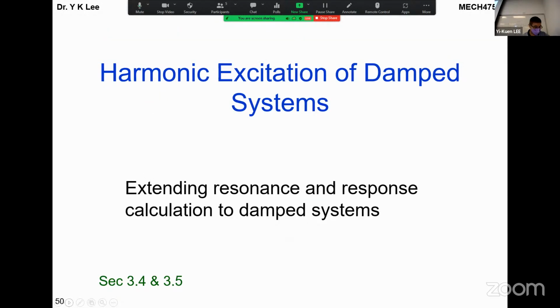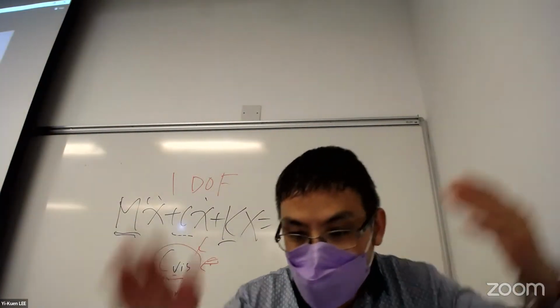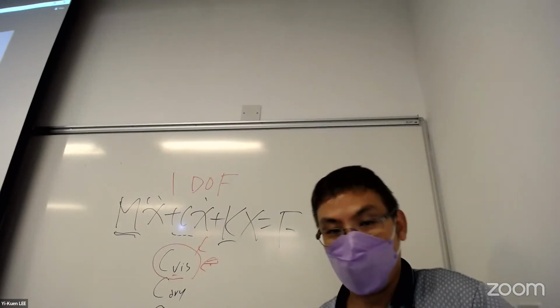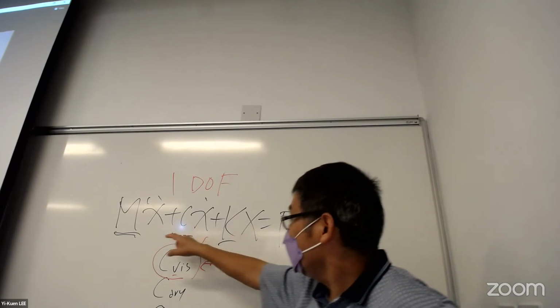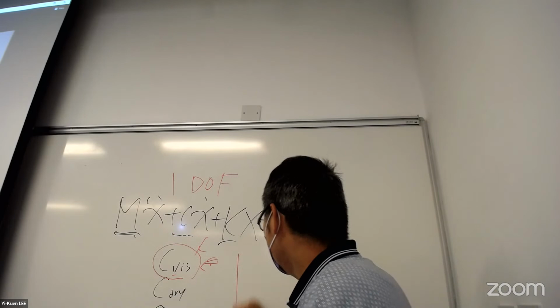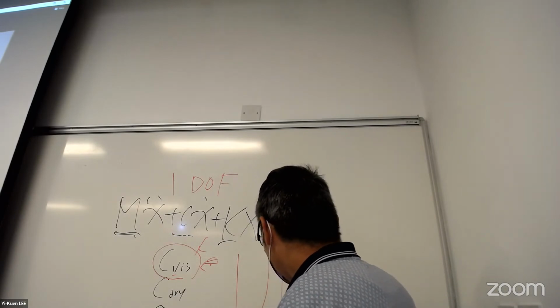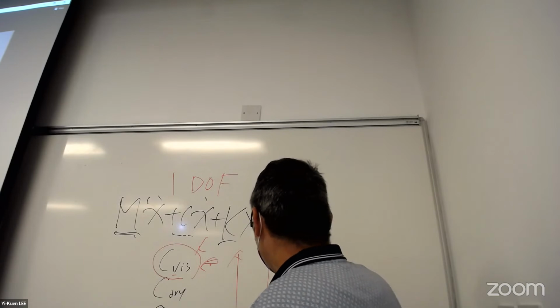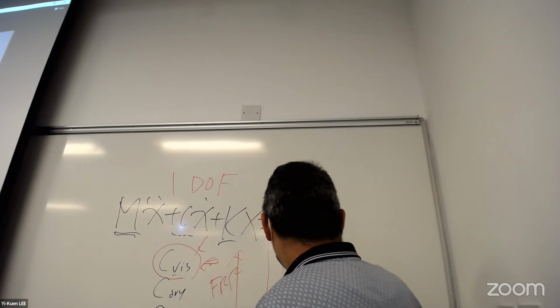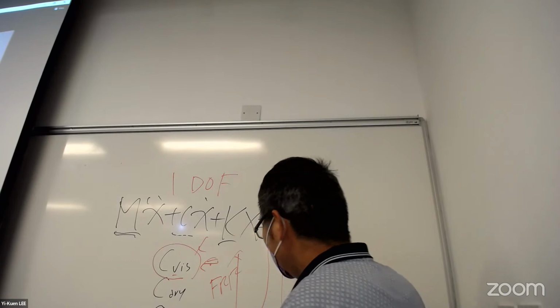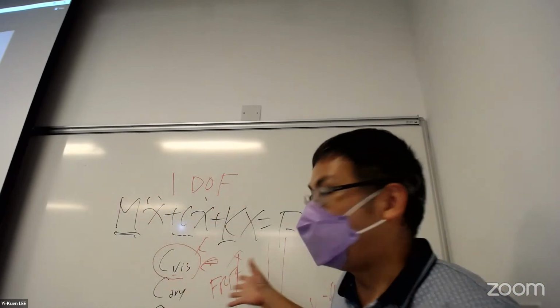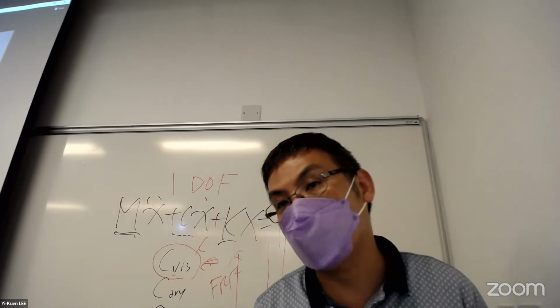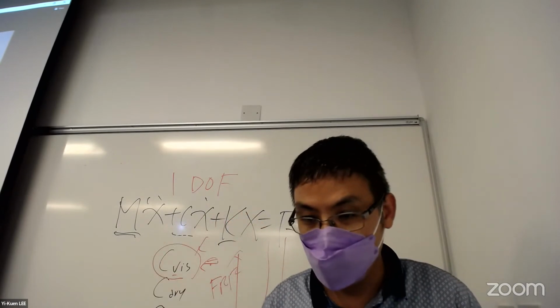Okay, I think we will run out of time. Today we tried to give you a brief introduction about this kind of frequency response, the MCK model under harmonic vibration, and how we can describe this kind of response. This is quite important. Now you need to think about frequency response as a function of omega over omega n, so that equals R. We tried to give you this concept, and this is one of the important tools for practical vibration engineering.